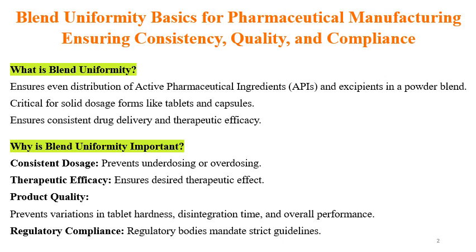The solid oral formulations can be made through different techniques like wet granulation, dry granulation, slugging, roller compaction, or direct compression by blending and lubrication. So, blend uniformity is required in the blend to have homogeneous distribution of the drug substance.